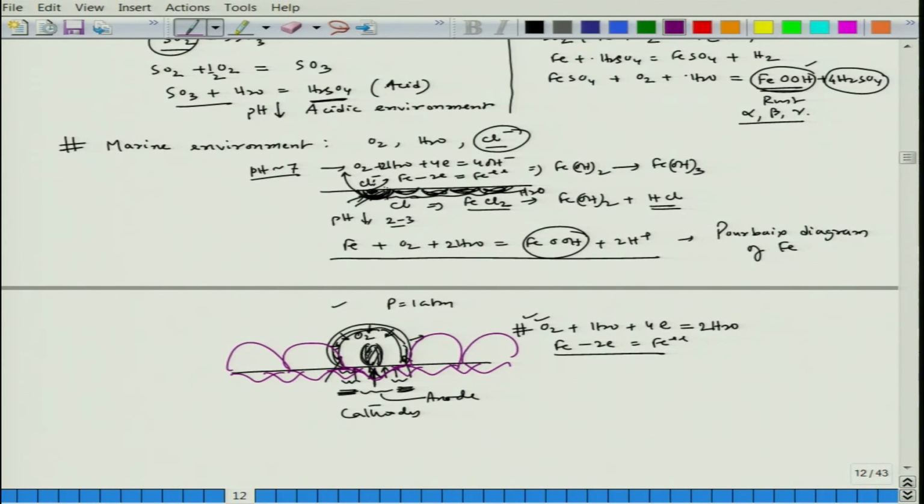And interestingly, I am not getting into the detail of it, you can guess that there is an influence of galvanic mode, and this is my experience that whenever we talk about uniform corrosion, it is actually happening due to a galvanic mode. Some part is becoming cathode and some part is becoming anode, and after some time, for example, if the raindrop stays here only, you will see there will be a pit formation at the center of the droplet. Around that you do not have anything.